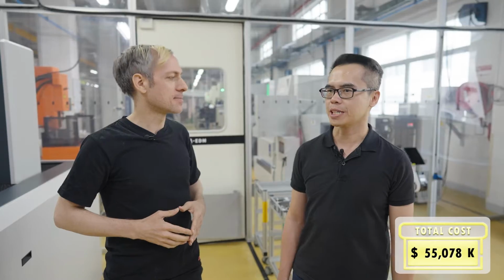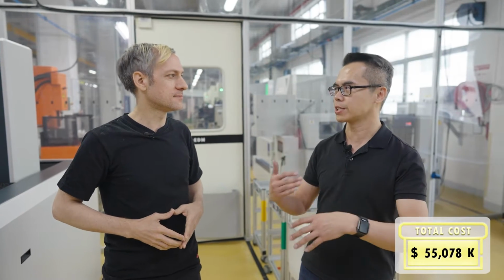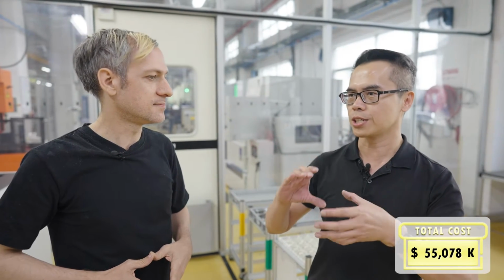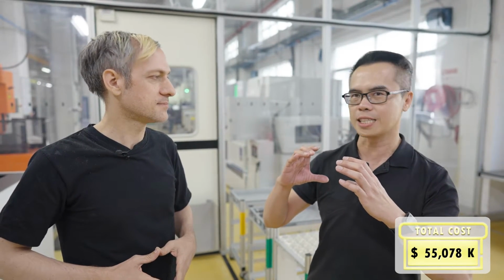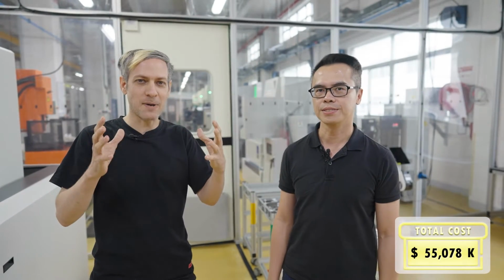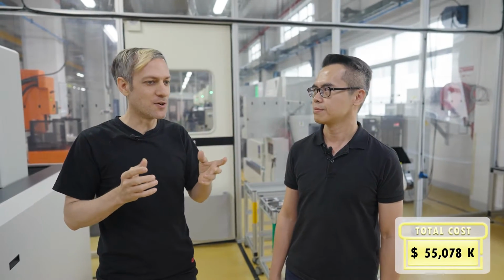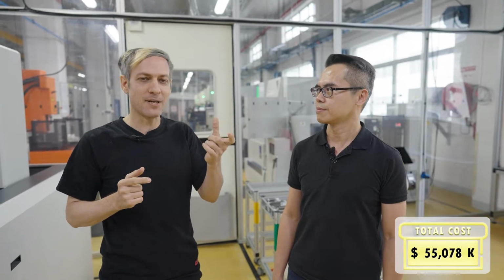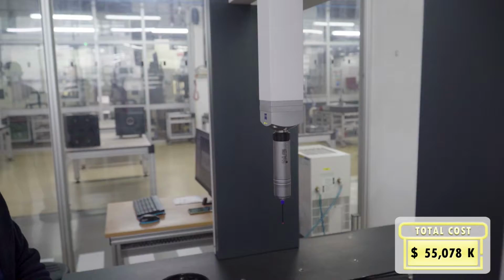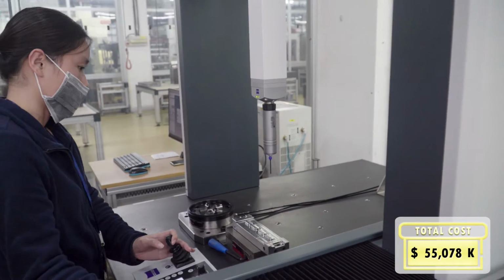Really? Because we need to control the temperature to ensure all the objects before the measurement are at a precise, consistent geometry. Basically, any change in temperature, the parts will get warmer and expand, or get cool and shrink. So if you're going to measure accurately, you've got to keep it at an accurate temperature. Exactly. So let's see how we measure the parts.